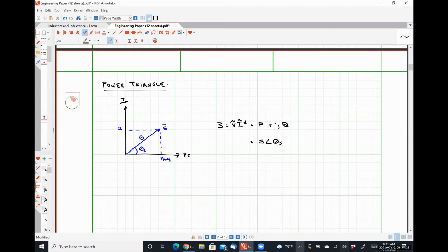What I typically tell students, doesn't matter if they're circuits 1 students, circuits 2 students, whatever: at this point, once we've introduced the concept of effective values, it does not matter what power quantity I ask you for, other than instantaneous power. You should just calculate the complex power and then use that to get your other quantities, because they're all built in to this one little thing.